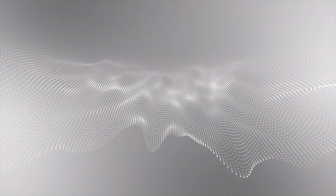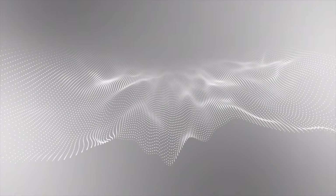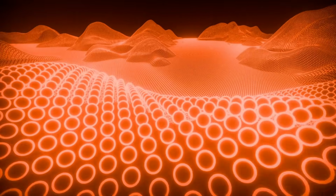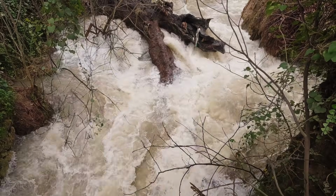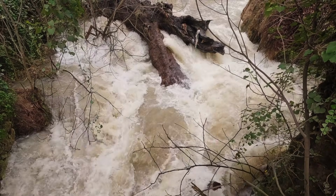modern engineers use computational fluid dynamics, which divide the valley into millions of tiny cells. Each cell calculates the mass, momentum, and energy entering and leaving it every millisecond. But even these models struggle with the transition of the water from a liquid state to a polydispersed granular flow as it picks up sediment.